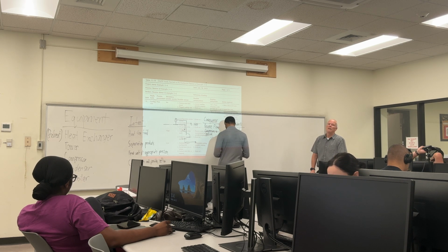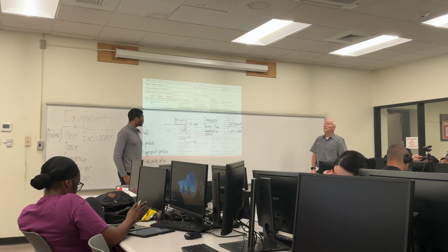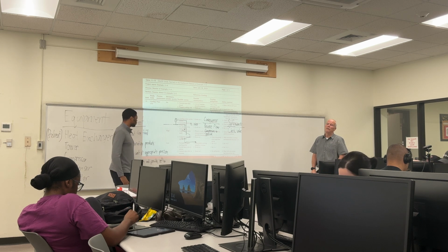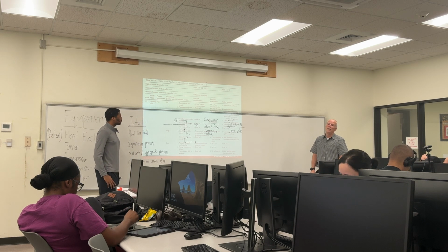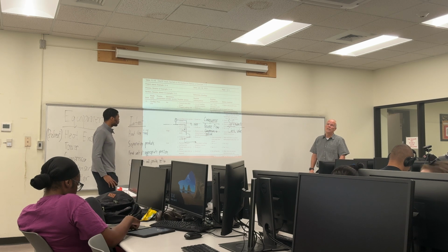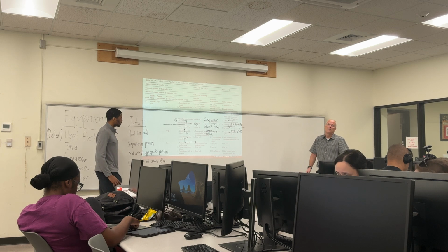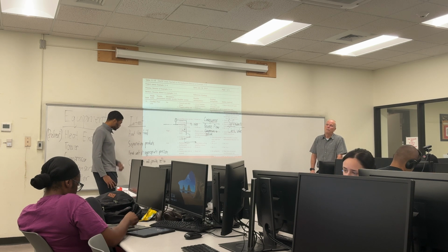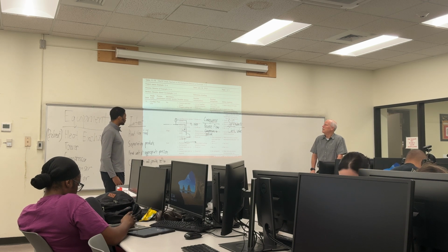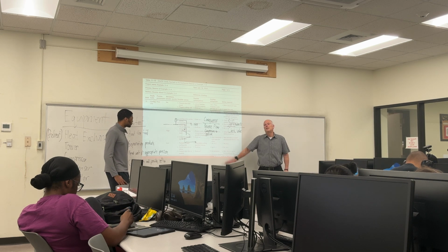Yeah, those compressors, they have these valves too, that they try to operate when they stop, because what's another thing that could happen to the compressor if you had this reverse flow and your check valve wasn't working? What would happen to the compressor if you didn't have that check valve? What do you think it'll do? It starts spinning backwards. And what happens to a compressor? It spins too fast. Tears itself apart. It breaks. Kind of violently too. So another potential consequence would be compressor damage.